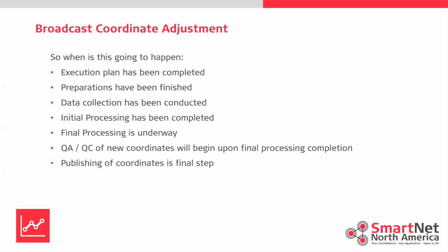Final processing is underway. It actually started, I think, this morning, or it will start tomorrow, one of the two. So this is basically 2 weeks of data, and we'll talk about that in a second. Once the final processing is done, we will QA and QC the new coordinates. So this is a large undertaking where we look to see if we have any flyers, any outliers, anything that doesn't quite look right.